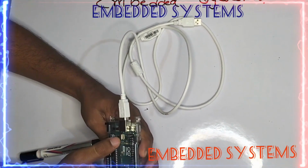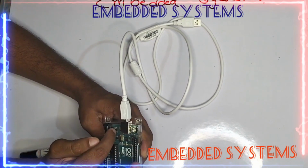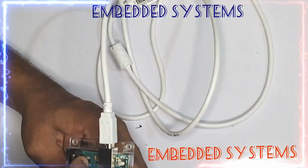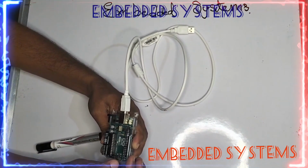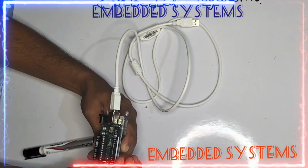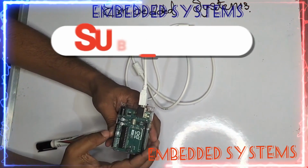Here it also has a crystal. The crystal is used as a reference clock for the CPU and the entire board. Here is the voltage regulator, taking 7 to 12 volts and regulating it to 5 volts, handing it over to the board to function in a normal manner, friends. It also has a UART, so UART signals are given here, and this is the ICSP, the in circuit serial programmer, but we are using the USB, friends.